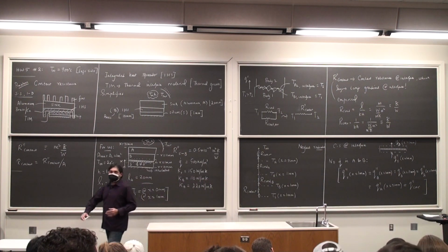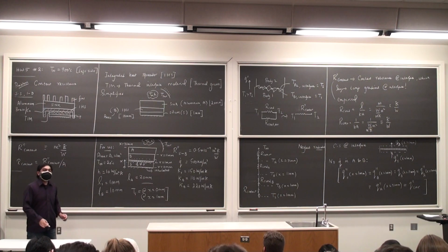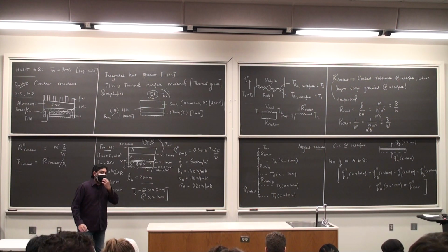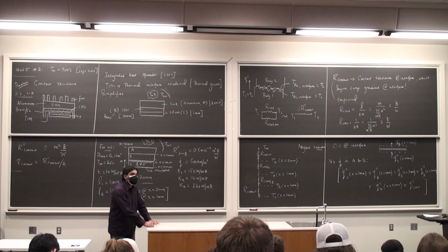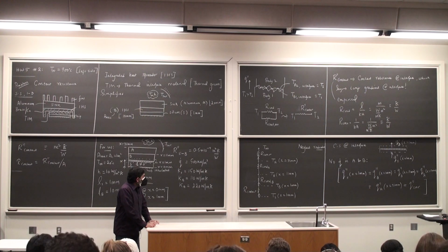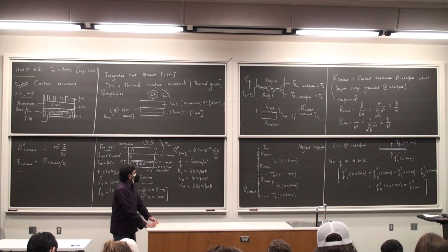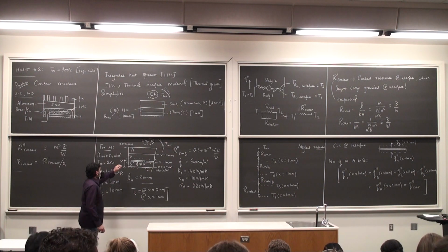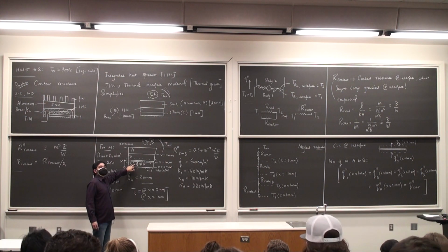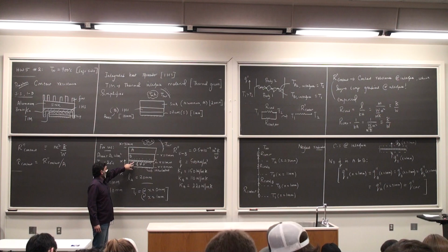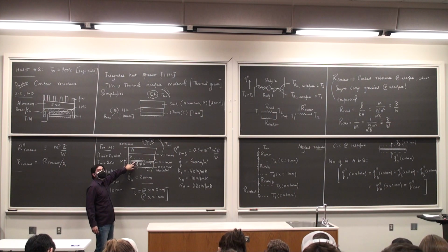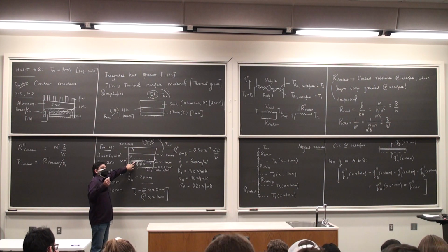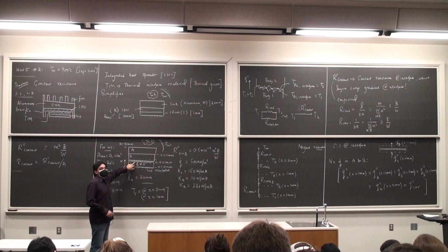Any questions, please? I've been rambling on for some time. Yes, on our resistance chart, we never talked about the temperature at x equals 0. I guess why don't we? Temperature at x equals 0 is because you see there is heat generation taking place within the silicon chip, and so I cannot really draw a resistance through the silicon because the conductive resistance is defined only when there is no heat generation.